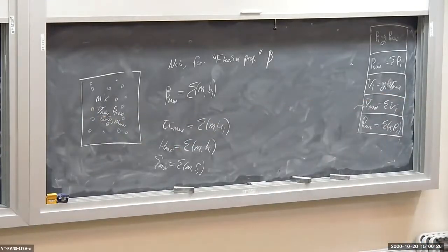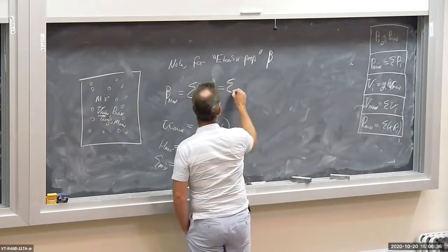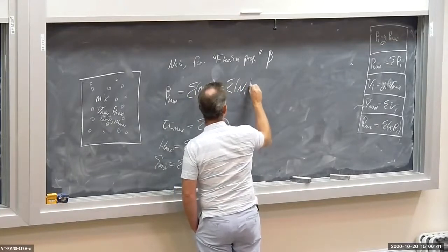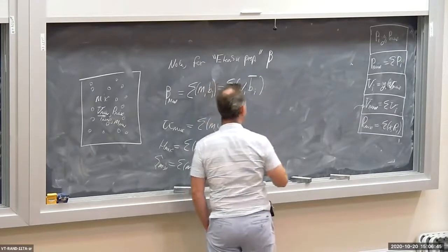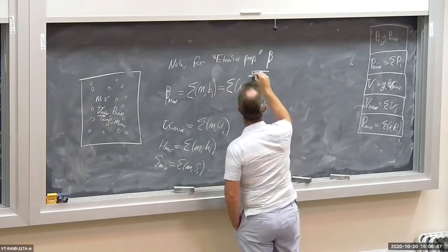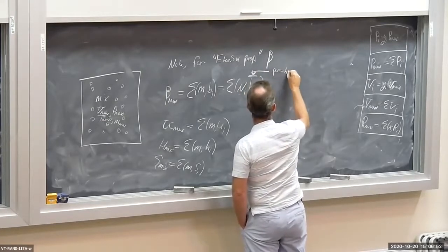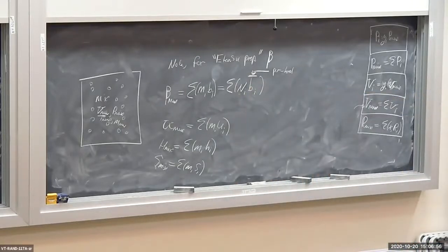Very easy to calculate mixture properties. You just sum up the property for each component, just sum them all up. We can also write this in terms of moles. We can say the sum of the number of moles of component I times B bar. That would be on a per mole basis. So this B bar is per kilomole, not per kilogram. That's what the bar is about.